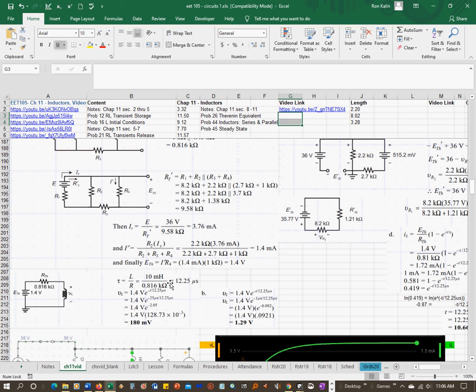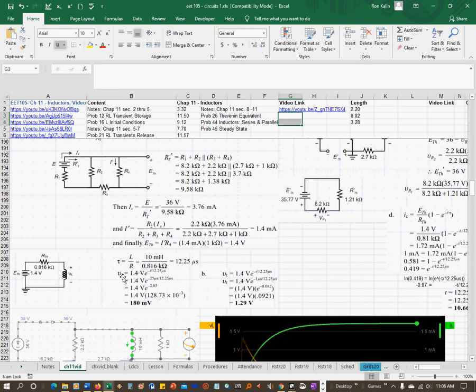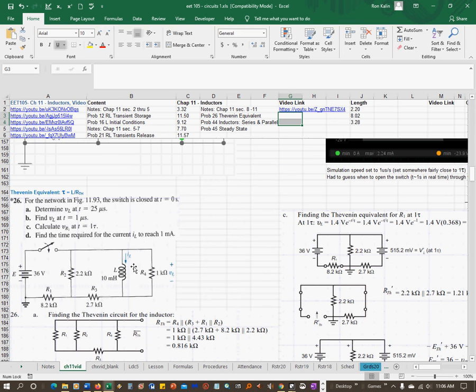You calculate that out. Since this is a storage problem, you use the storage equation and you plug in your values. In this case, E Thevenin you put in for E because you simplified it down to this circuit. And then you plug in your tau here, and the problem asks you to find VL at t equal 25 microseconds.